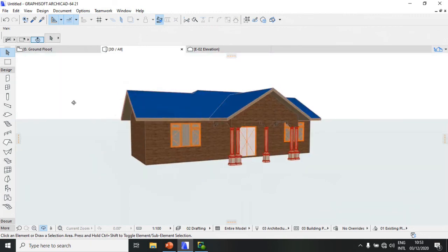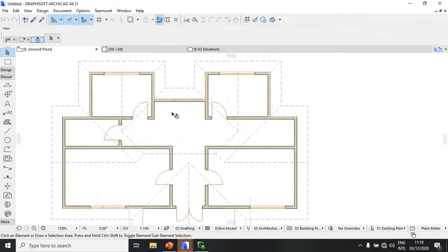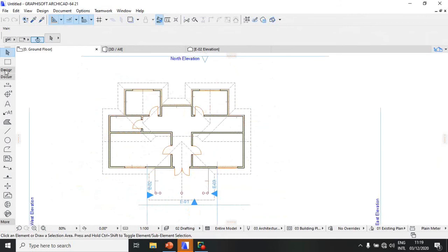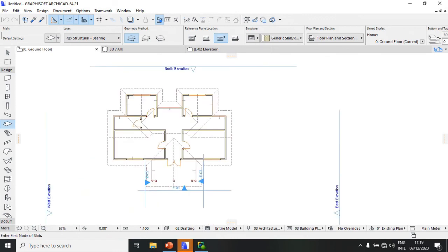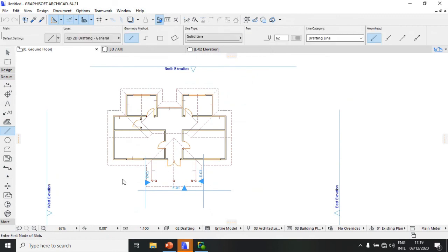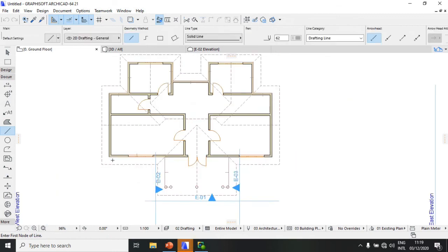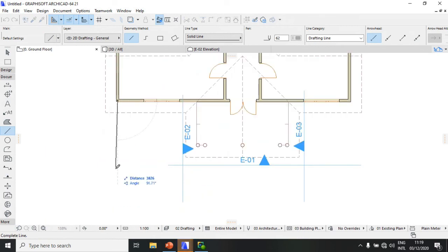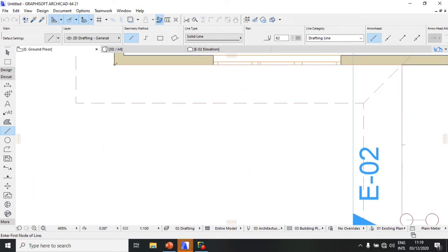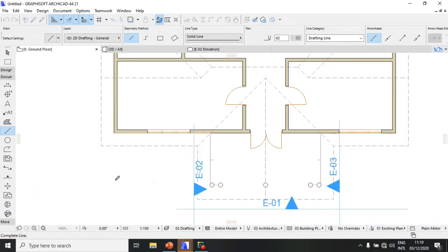So we can add our slab there. We are going to add the slab. So we go back to the design, slab tool. But first I'll go to documents, then I'll pick the line tool. I'll draw a line from that point, escape, from the corner this way.